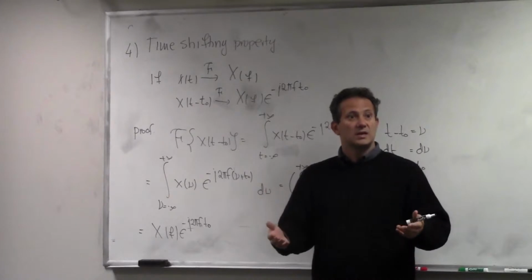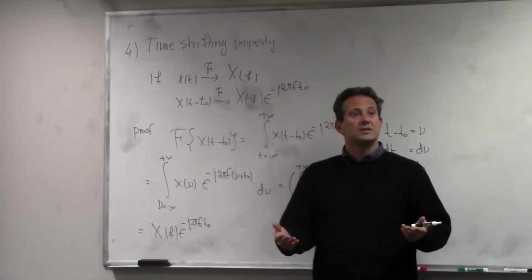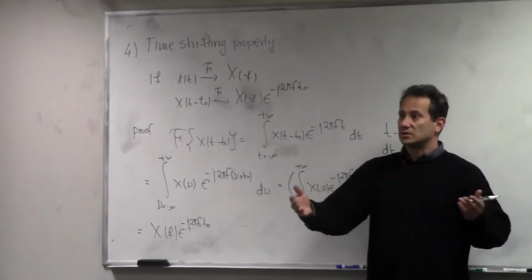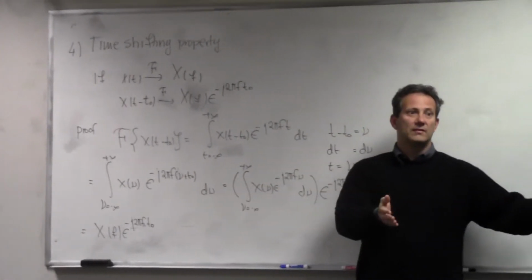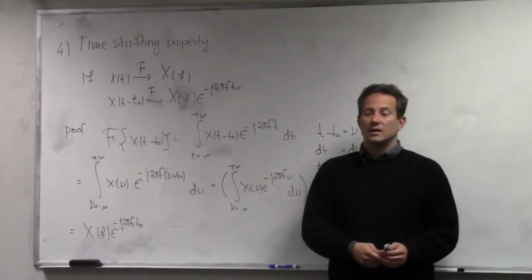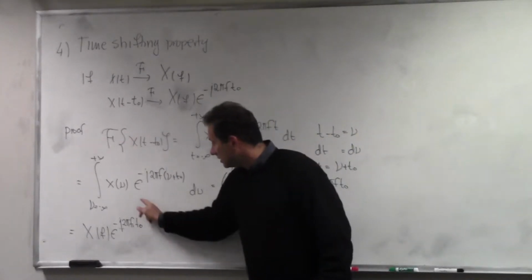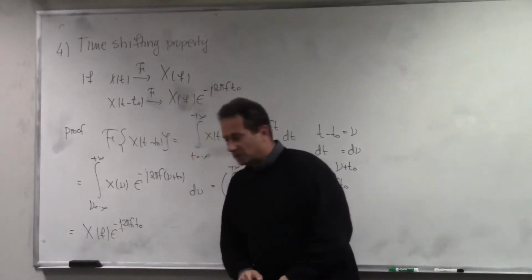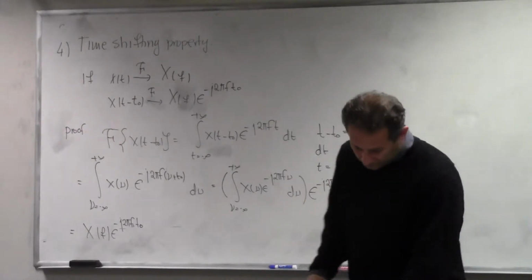It's the very same sinusoids, and it's in the very same proportion that I need to add them. What changes is their phases, because I need to now align them with the reference to a different time. And that's why there's a change in the angle spectrum, or in the phase spectrum, and not a change in the magnitude spectrum.